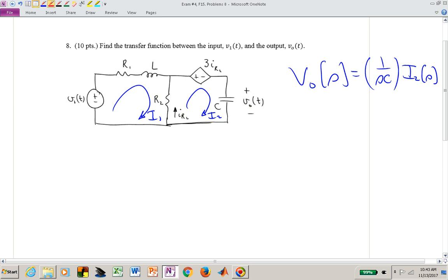So if I was faced with this and somebody was giving me this problem on an interview and I got a little bit frustrated or flustered with the assignment, I would say, you know what, let me just go ahead for now just to give me something to not struggle with. Let me replace that dependent source with R sub 3, and I can at least show you that I can analyze a very basic circuit problem.